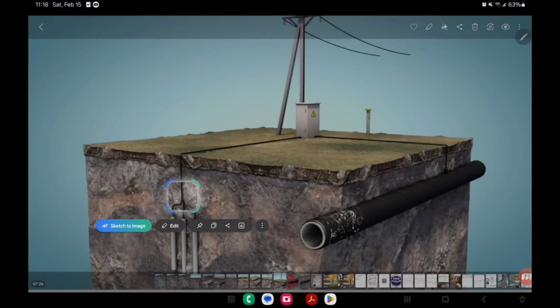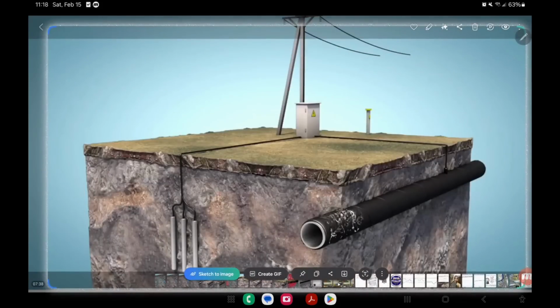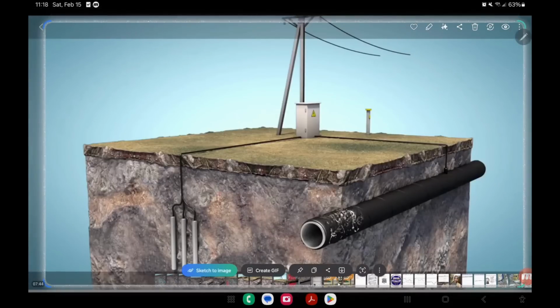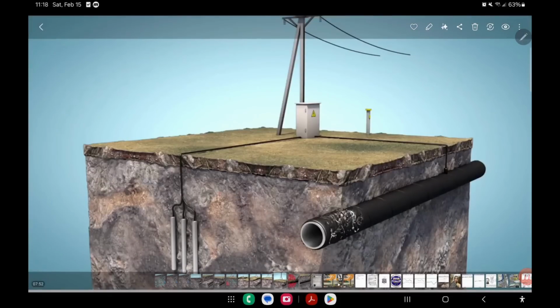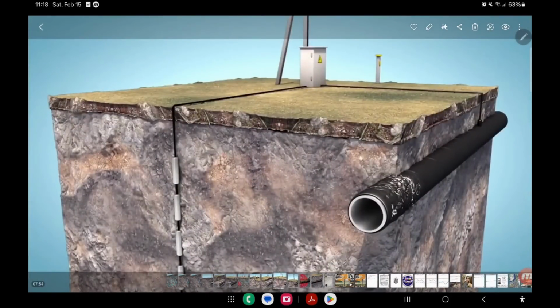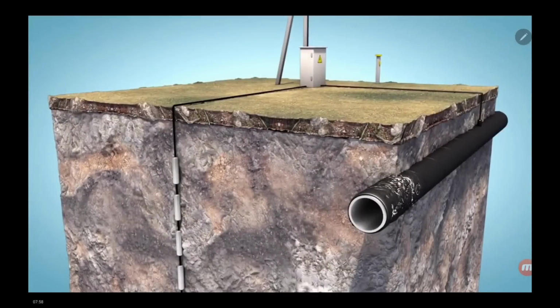That would be the common point with vertical anodes, but we, as corrosion specialists, have to adapt to the terrain conditions. Whether it's because the circuit resistance affects us a lot, the resistivity of the terrain, the resistivity offered by the electrolyte, and that's why we have to make configurations. This is indeed one of the examples, but here we have another example of vertical anodes, but in series, or the famous deep ground beds.